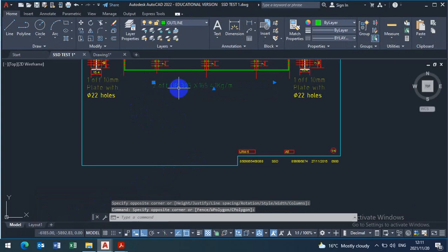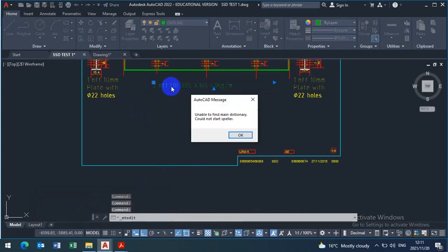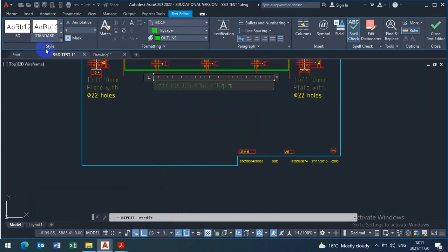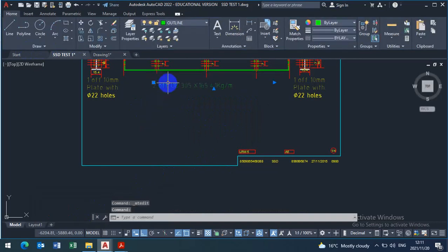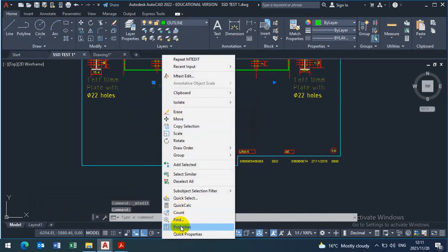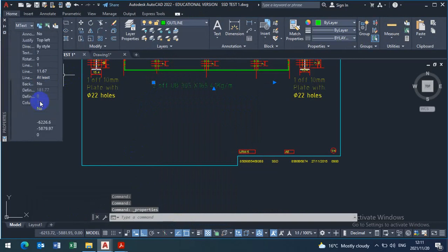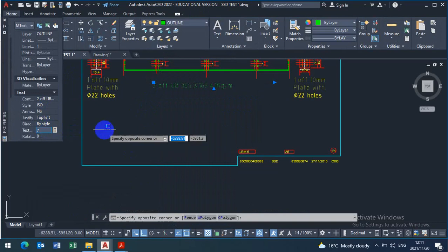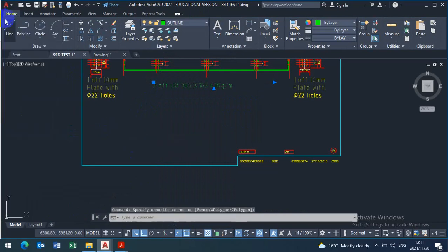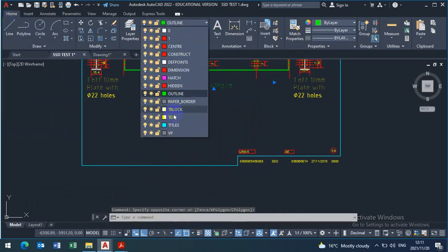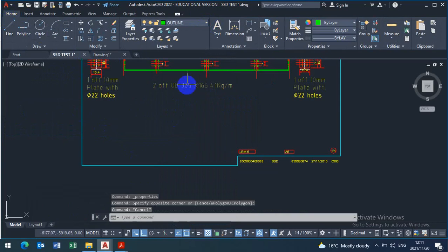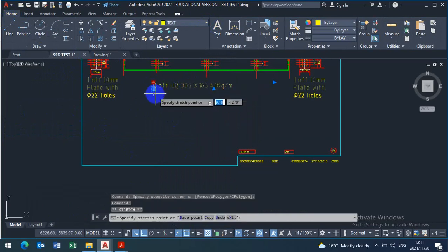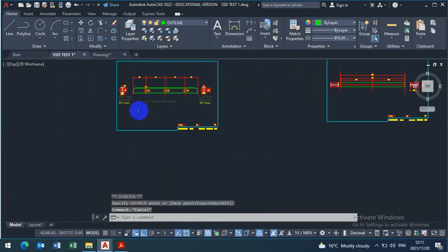This one should be size 5 millimeters high because it's the main heading. 5, or yeah, it's on that one. Or you can right click, you go to properties and change the texts under text size. Yeah, 7 or 5 is fine, and then put it under text layer and then move it nicely there in place.